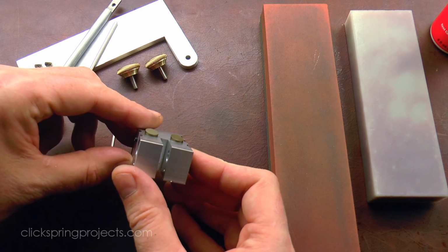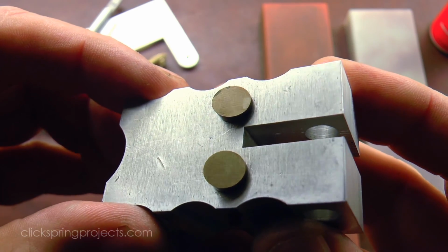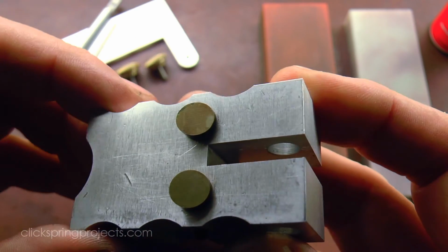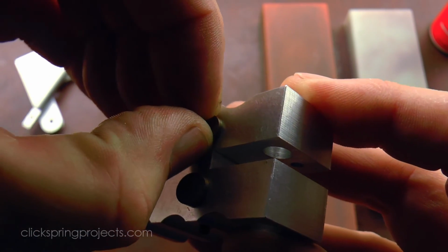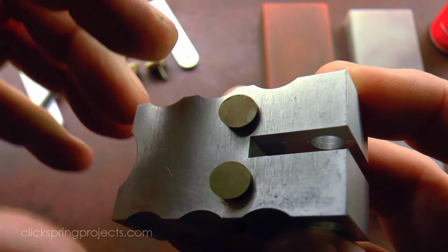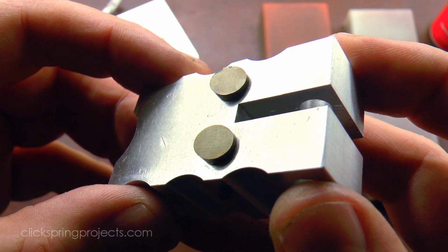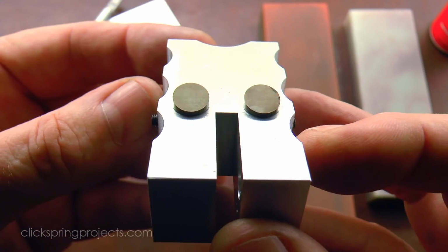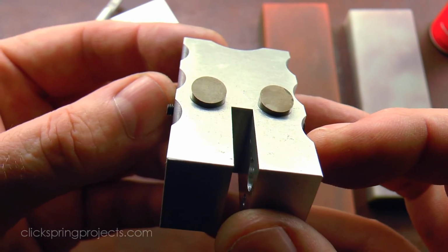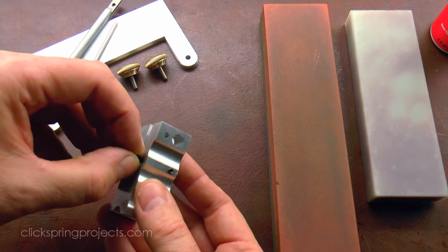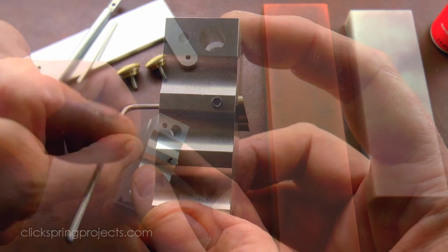And depending on how the parts have been held in the mill, the tool marks can be of use in getting this alignment as close as possible. The lower grub screws are then inserted and the buttons are advanced so that each sits the same amount forward of the carrier face.